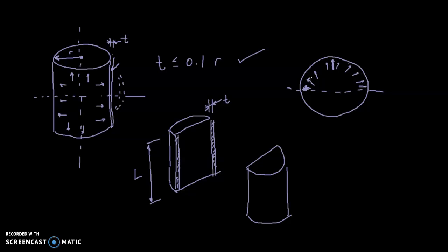If we were to add up the vertical components of all of these force vectors, we can say that it's pushing up with a combined force of all these vectors of P. Big P is the force pushing up. And so that force is going to be resisted by this wall and this wall, these two walls here, the outer walls of the cylinder.